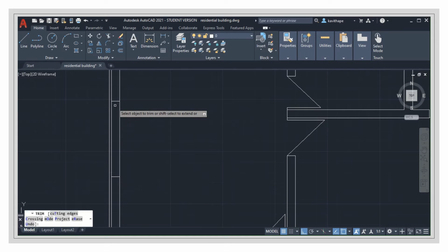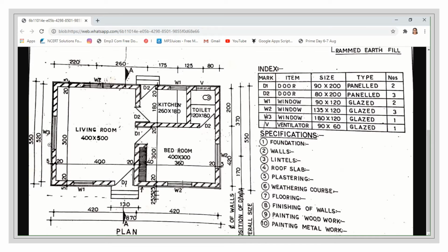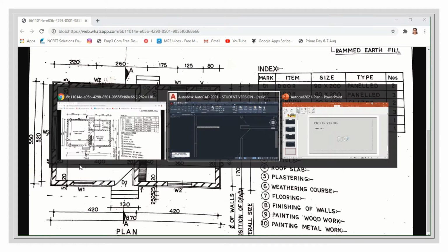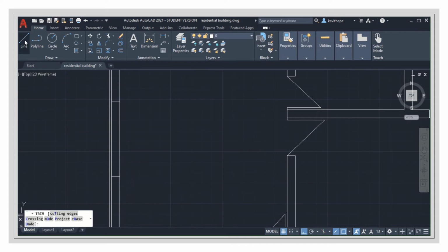Now we shall draw the double line as specified here. Here you can see there is a double line. So first of all I am going to draw a line. Since the object snapping is there, you can see the snapping settings can be done at the bottom right. Since it is on, a triangle will show the middle of the line. Again moving the cursor, a triangle will appear. Only when the triangle comes you click. So it will correctly snap at the middle of the line.